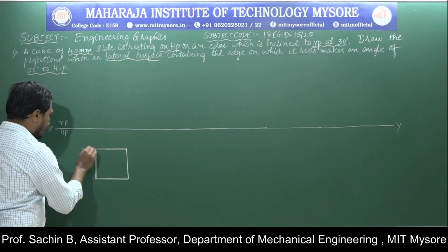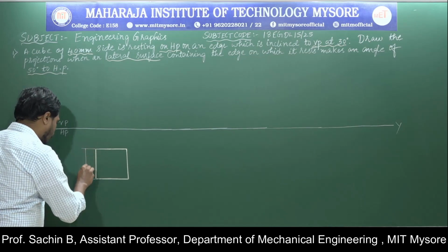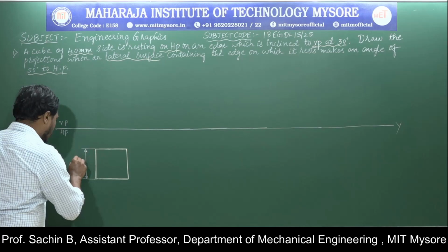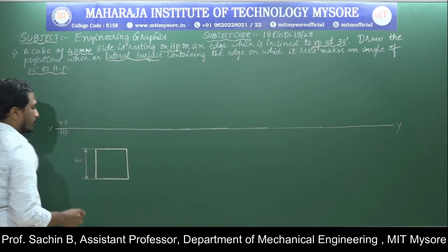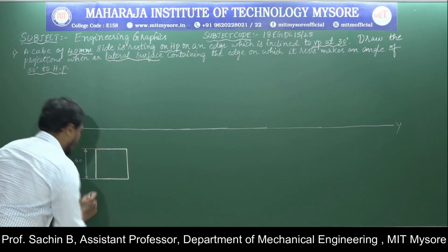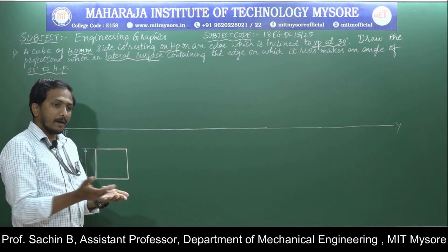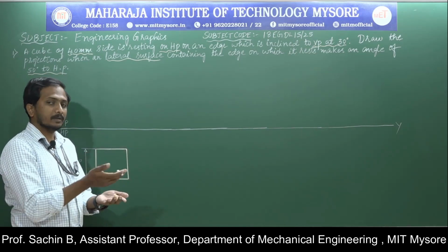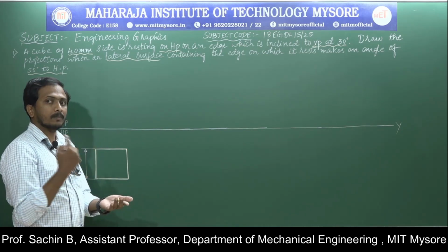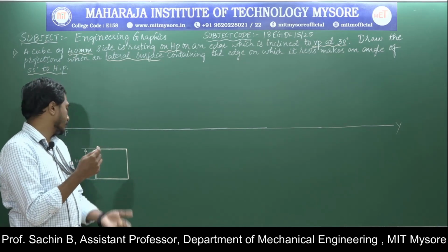Next I will draw the projection lines and dimension line for indicating the dimension on any one of the edges of 40 mm. Now I'll name the corners. Now it is a cube. Here in the cube, the base and the top face have the same square shape, and it is bounded by the square shape in clockwise or anti-clockwise direction.